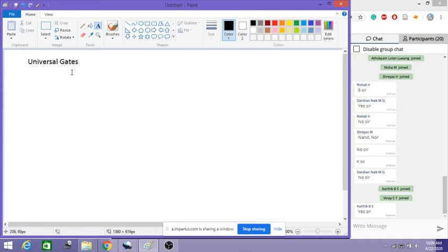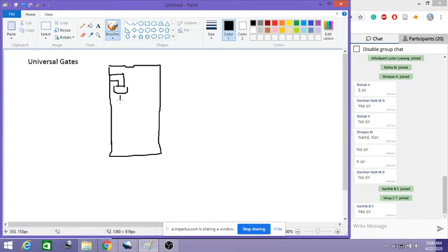If you have seen the ICs of AND gate and OR gate, basically it will come with a package. It means if I write here the IC, the integrated circuit, basically it will have 14 pins, and internally I'm not sure, they might be 1 and 2 are input and 1 is output. So this is 1 2, these are pin numbers 1 2 and 3. Then likewise I'll have here, then 4 5, then 6 is the output.